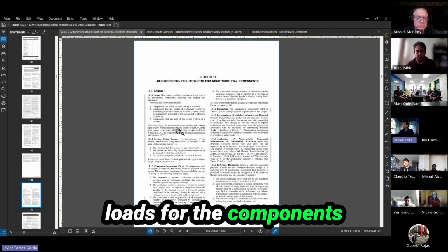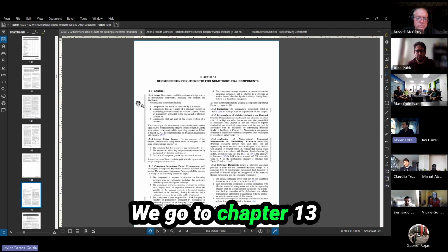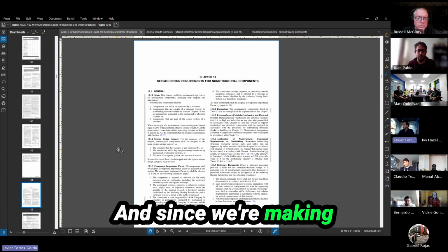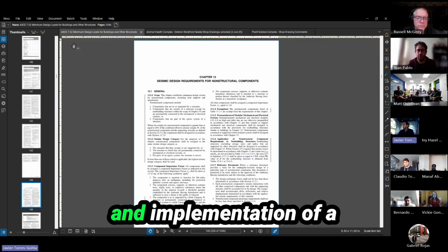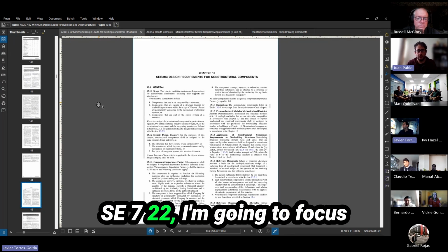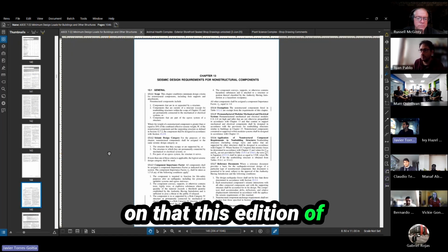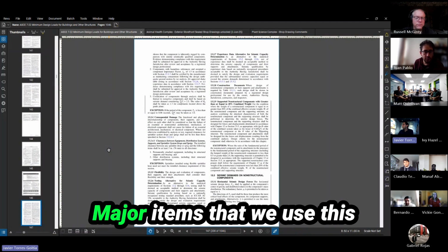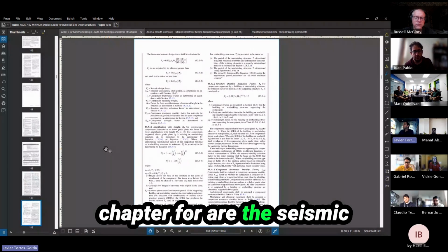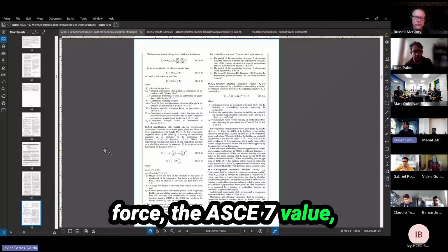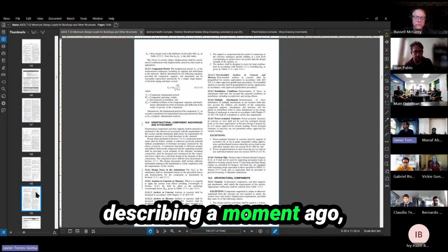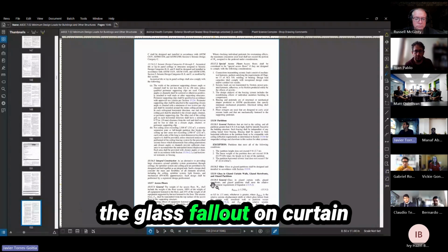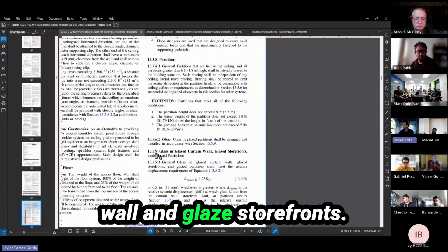For the components that we typically design, we go to chapter 13 of the ASCE 7. And since we're making this video after the release and implementation of ASCE 7-22, I'm going to focus on this edition of the ASCE 7. The two major items that we use this chapter for are the seismic force, the Fp value, which is what I was just describing a moment ago, and particular to our industry on glass and glazing is the glass fallout on curtain wall and glazed storefronts.